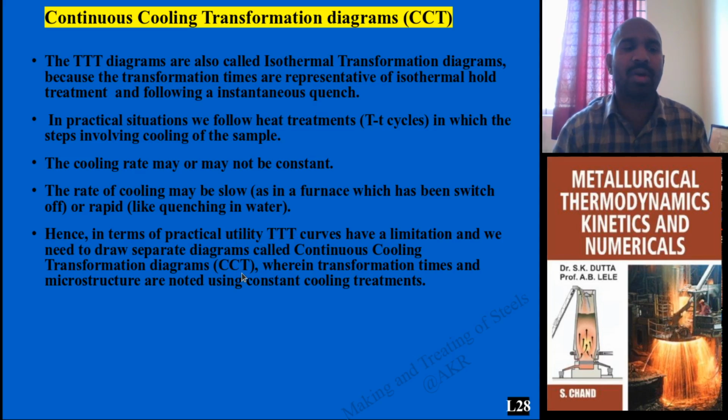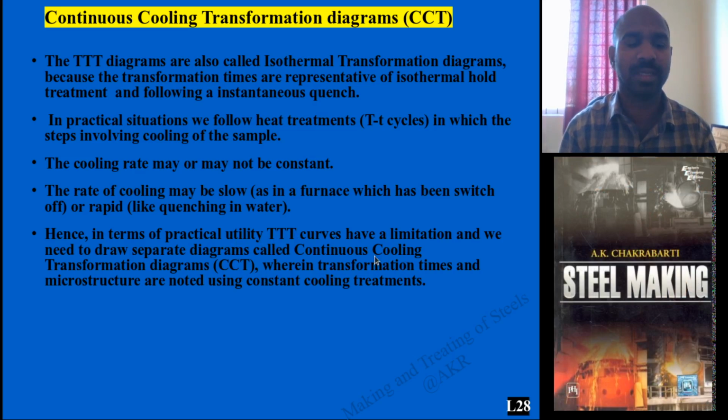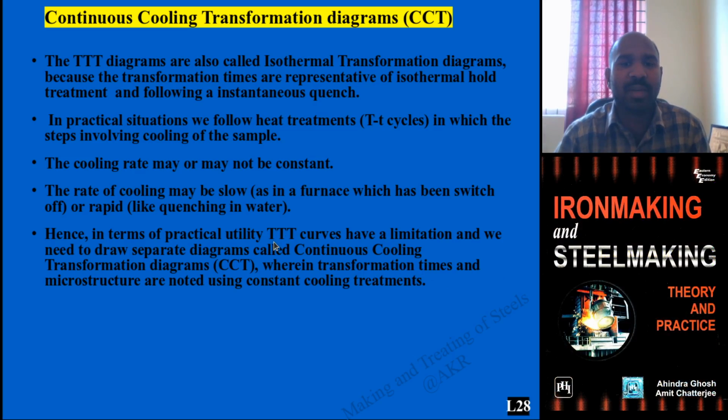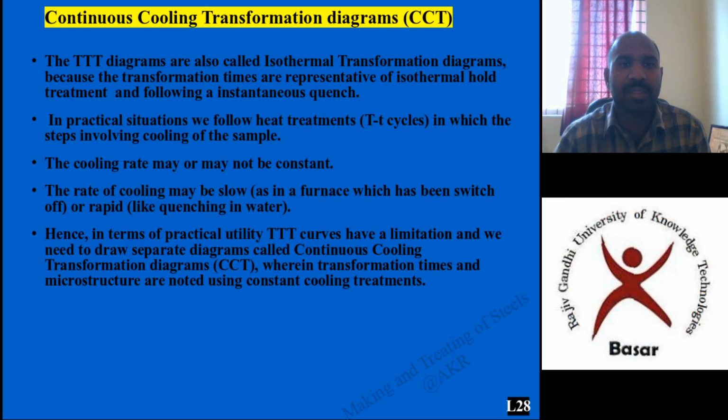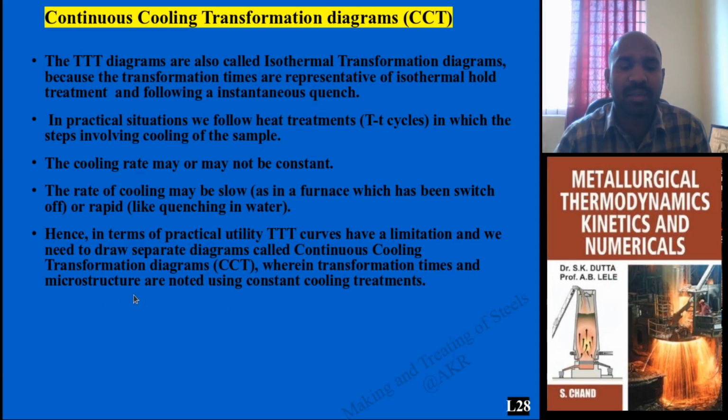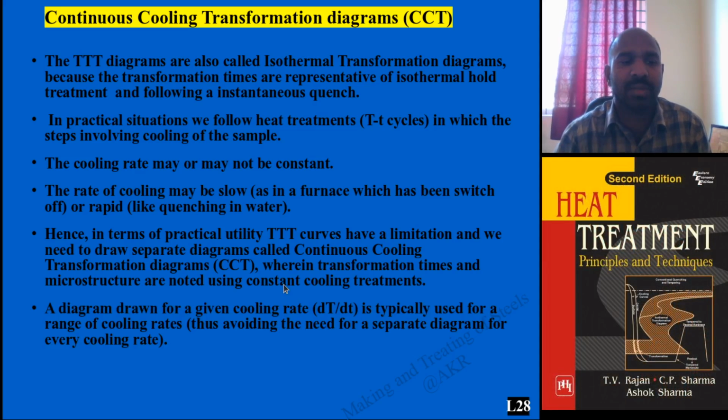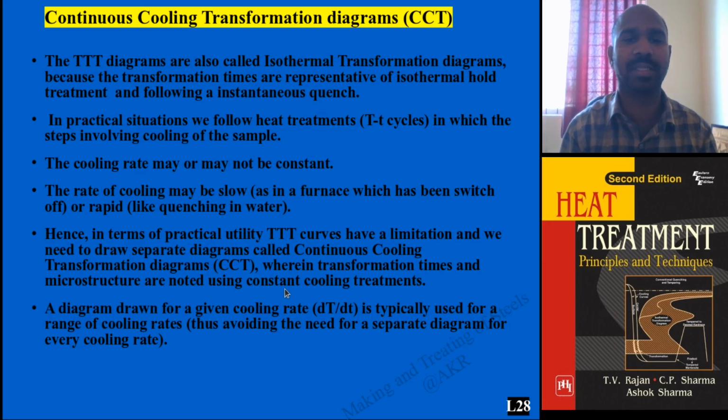But drawing separate cooling transformation diagrams, as continuous cooling was occurring, is very difficult. Even the cooling curves are plotted in one single graph with varying time and temperature, which is addressed in the continuous cooling transformation diagram, where the transformation times are also represented and microstructures are also noted with the continuous cooling treatment. That is this diagram's speciality.